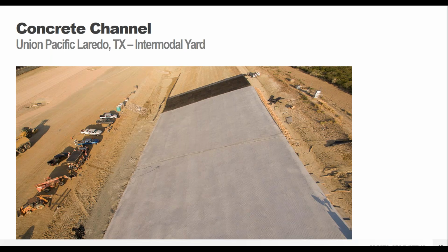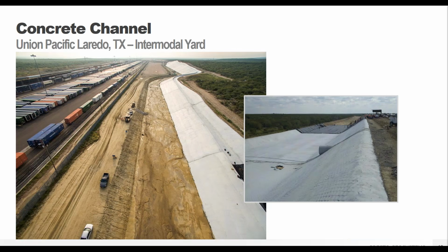Pore pressure buildup is always a concern underneath concrete structures, and it is here as well. So we do recommend doing something to address pore pressure buildup. That could include things like drilling weep holes into set concrete, or including drainage pipes before you pour in the concrete. You can install those through the GEOWEB panels. There are a number of different options that we're happy to give our advice on, but it's definitely something that should always be considered when using concrete for structures.